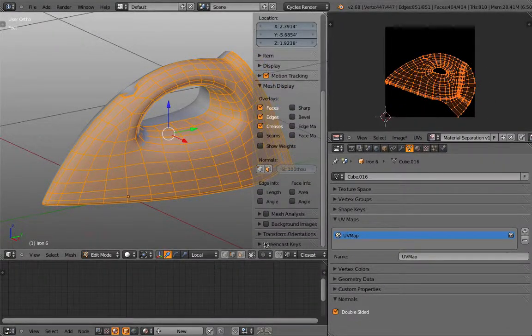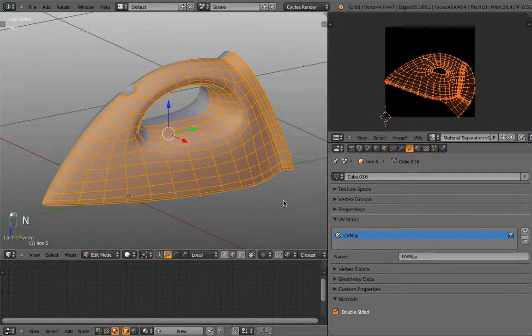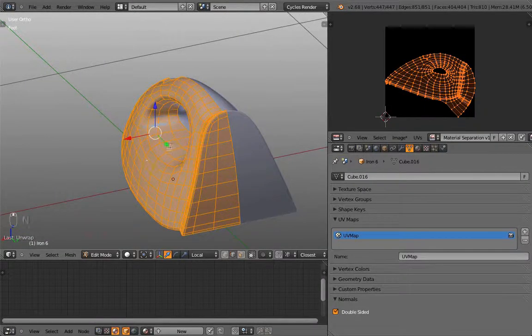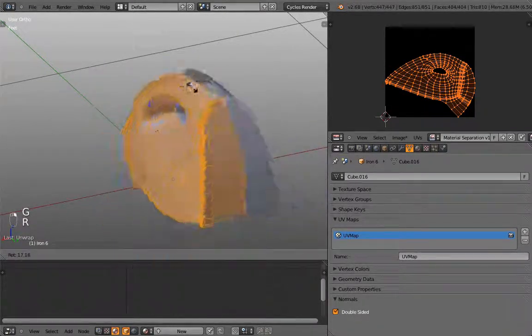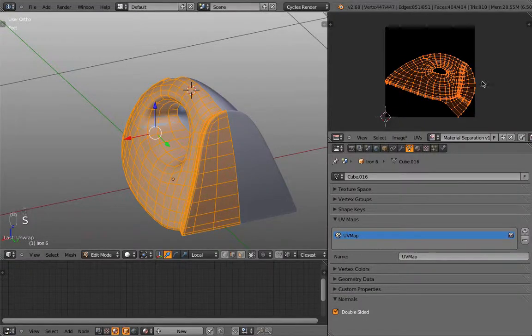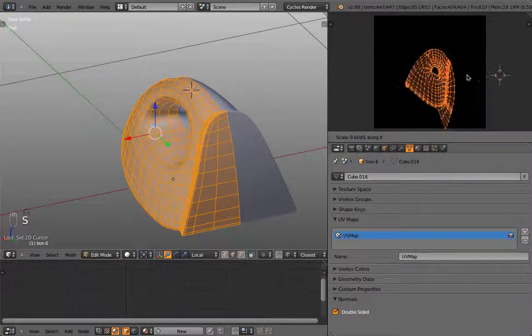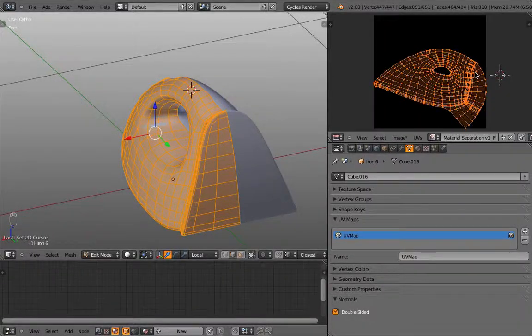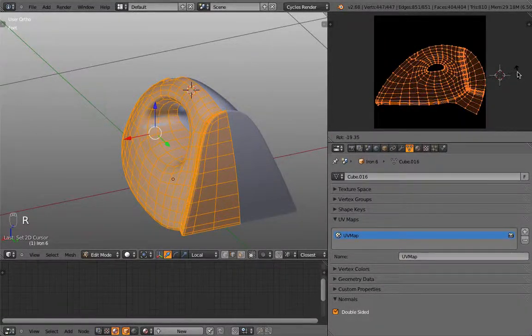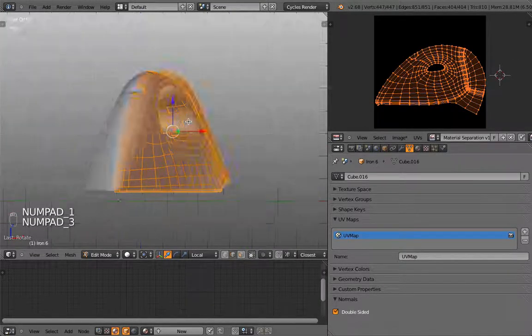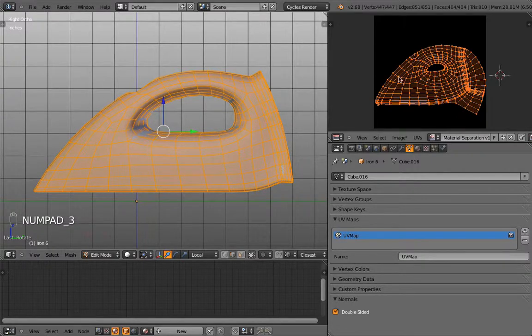And also something for you to keep in mind, and that's one of the nice things about Blender. Whatever you do in 3D view with G or R or S is exactly the same inside the image editor. So I can press R, G, and S, even with X or Y. So I would like to rotate this UV layout a little bit so it's not awkward, because my model is oriented horizontally, and now this unwrapping is horizontal.